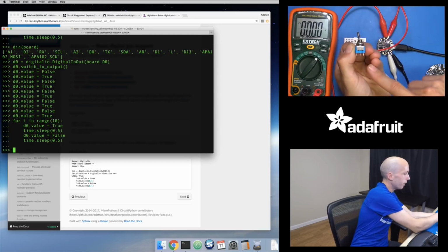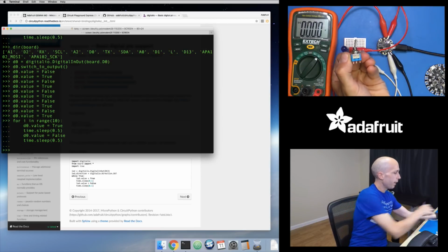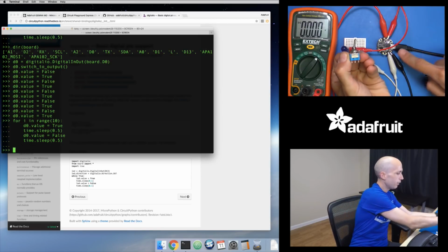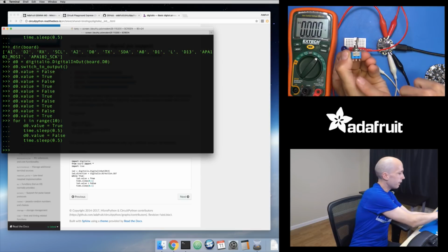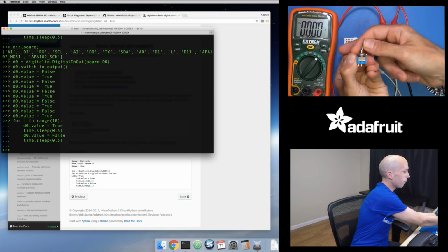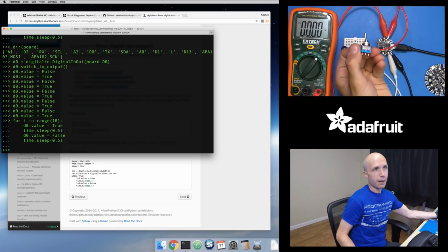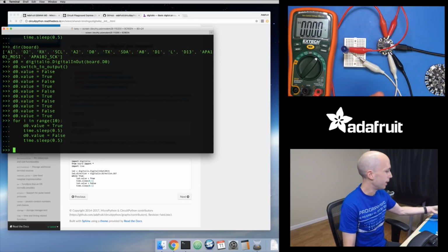So I could have, maybe, one signal that's on this side and now it's connected to the center, and then I have another signal on the other side and now that's connected to the center there. So the easiest way to start would just be to say, let's connect this center pin to one of the pins on my board, and then let's connect on the left maybe ground, and on the right 3.3 volts, the high logic level. So I'll give both of my digital logic levels, both the high and the low logic level, as possible inputs. And then when I toggle my switch, when I flip it in between, I should be able to read that value. I should be able to read a high or low logic value from there.